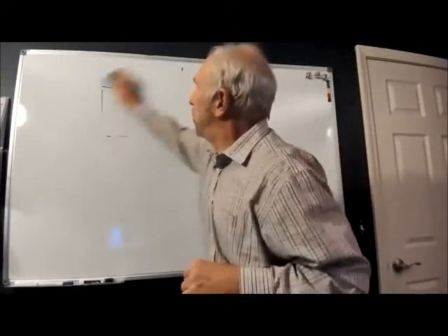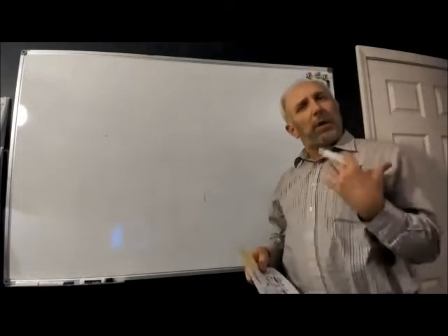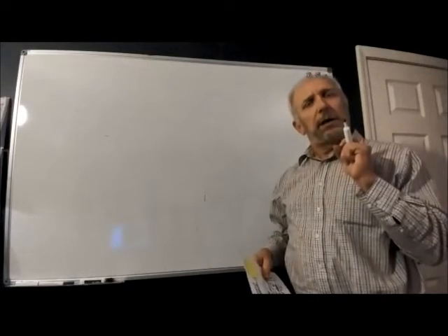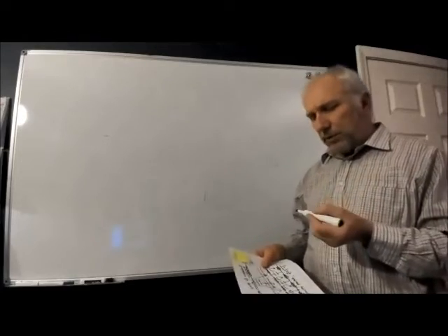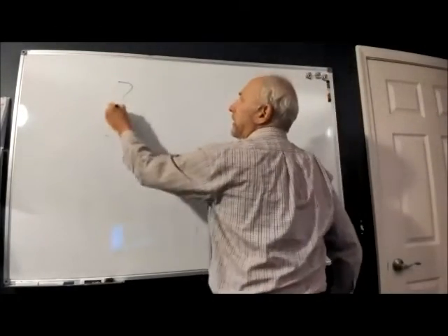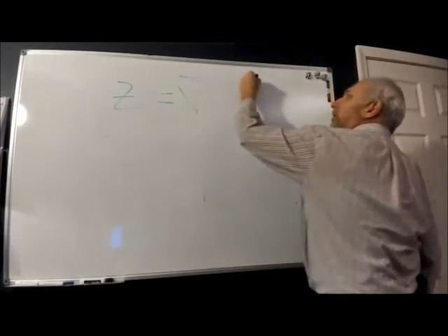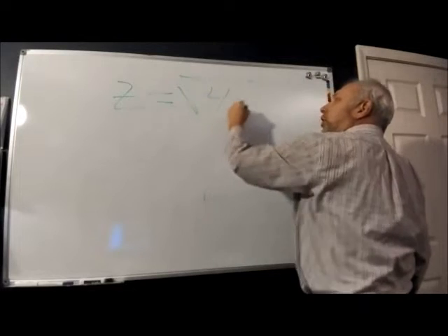And let me write that equation down. There's all kinds of mathematics behind this, but for the purpose of what we want to accomplish now, again, the key parameter is the characteristic impedance, and the characteristic impedance is defined as the following. Z is equal to the square root of L over C.